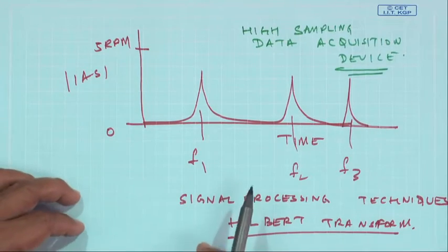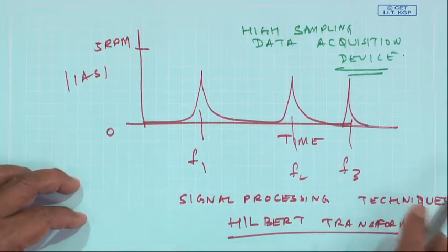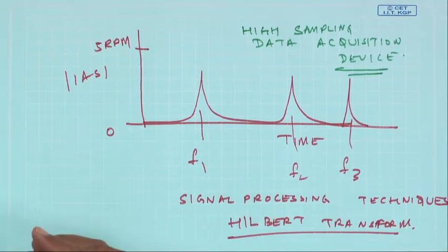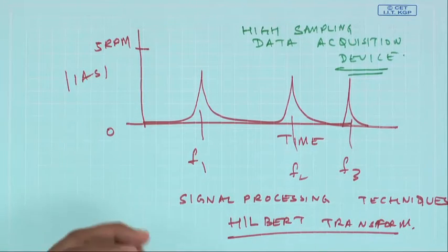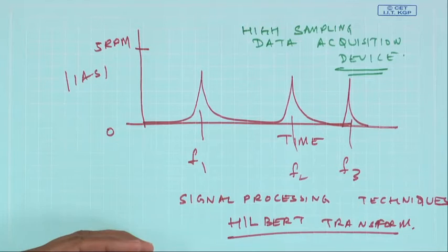So, such systems are in place, and we can find out the rotational speed. So, in summary, we discussed both the mean speed measurement transducers for rotational speed, like the reluctance type pickup, the capacitive type pickup, the phototach, the stroboscope, and of course, you can also use the rotational laser vibrometer.